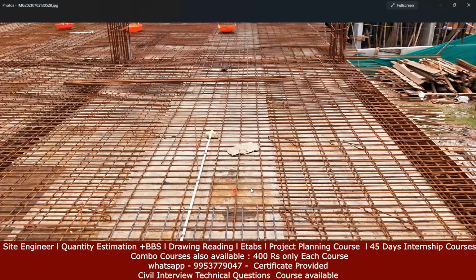What you can see, you can see the bottom steel here. You can see in the center portion in this way. This is your bottom steel which goes, and then this is your top extra steel. You can see from here, this is a top extra. From here also top extra. In the same way, in the other direction also, your steel will go in this direction. Similarly, here also that direction of steel will go. So in this way, whatever was there in the drawing, the same has been executed practically on the site. Again, the same bending moment diagram also follows here. We know we have negative, negative, and positive, and that is how the execution is done practically on the site.